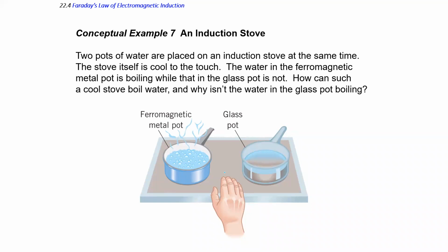Yes. On Thursday, I will try to have examples of what's going on here, because there's no reason why you can't do this with permanent magnets. When you go home, if you have a neodymium magnet at home, take it and an aluminum cookie sheet, if you have one of those, or just some large non-ferromagnetic material, and let one slide across the other, and you'll feel a resistance. And what's going on is, no matter the material, the magnetic field, or the fact that it's trying to slide, will cause a current loop in the metal.